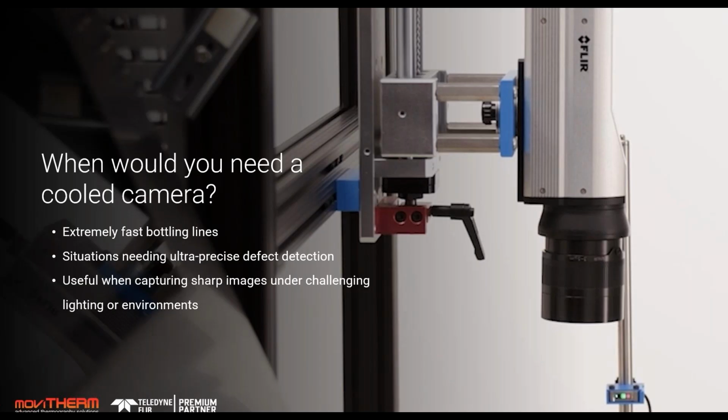Yeah, there's not a ton to this, but with an uncooled camera, as I mentioned before, we do need some time for that heat to conduct to the top of the cap. So you can't take the image too early. You can't take it too late when the heat starts to diffuse.